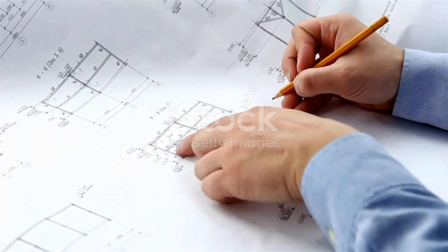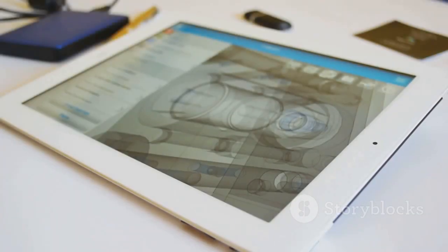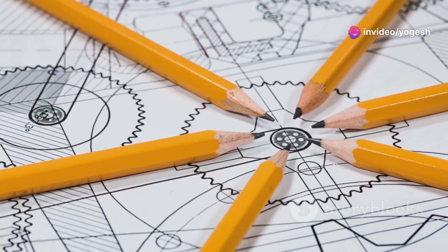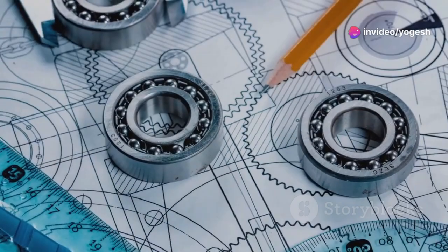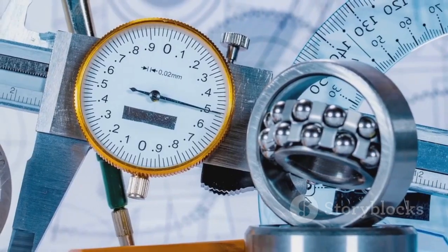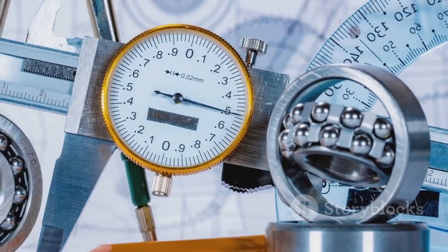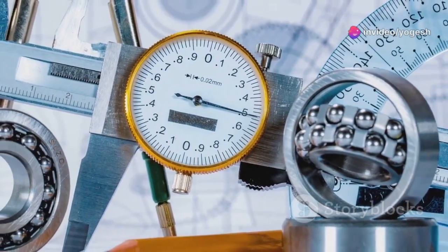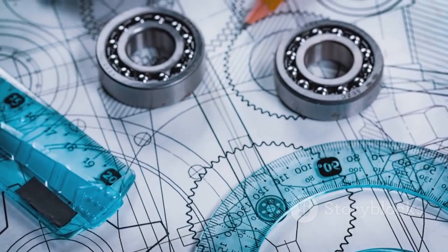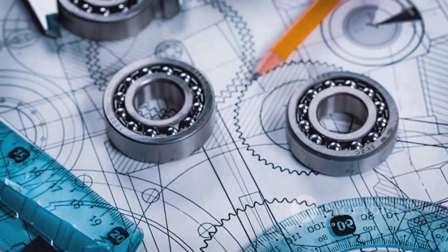What about features you can't see? That's where hidden lines come in. These are thin, dashed lines showing edges or holes hidden from view. Use them to reveal simple internal features without cluttering your drawing. But don't overdo it. If a view is crowded with hidden lines, consider adding a new view or a section. The goal is always clarity. Use hidden lines as a tool, not a crutch. If you see more than 10 hidden lines in one view, rethink your approach.